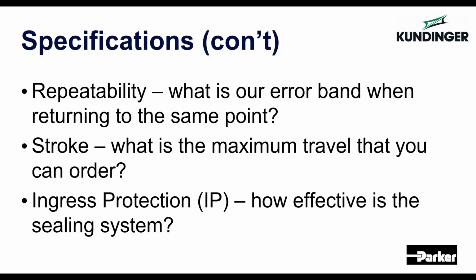So the first number, and we use the example of IP54, the first number is your ingress rating against solids, and the second number denotes protection against liquids. So IP54 meaning protected from limited dust ingress. So if you have fine dust in your environment, protected from that for the most part. And the 4 meaning protected from water spray in any direction, not wash down though. Think more of like splashing in that case.